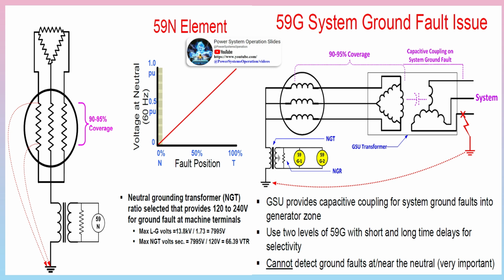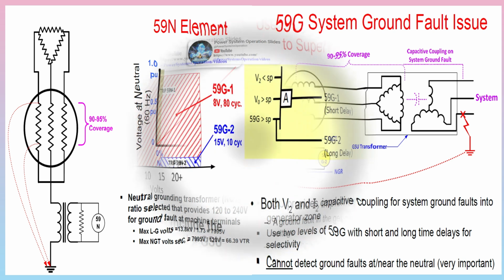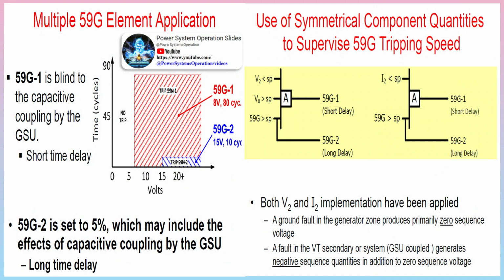Impedance from the grounding transformer, same as a high impedance grounded system does, mitigates generator damage from a ground fault. A reactor is tuned against the generator capacitance to ground to limit ground fault current to a very low value, which can be less than 1A. Hybrid impedance grounding has the advantages of low Z and high Z grounding in normal operation.